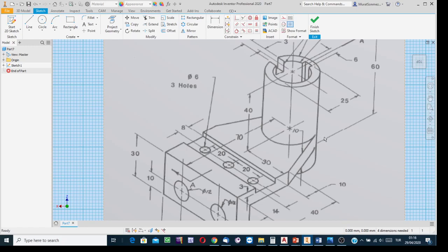If at the sketching stage there is a circle for which the size is given and the location dimensions for the center point are given, then you know the recommendation: first, create the circle or circles.